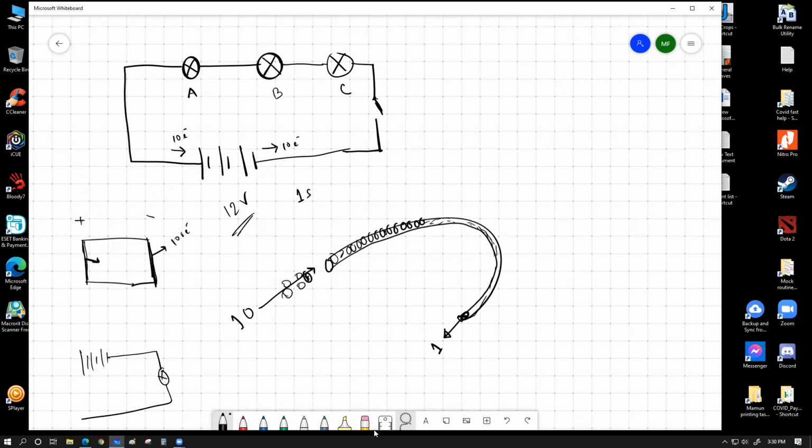You can assume actual or, realistically, 1 coulomb of electrons coming out of the negative side. Either way, 12 volt means 12 joule per coulomb, which means 1 coulomb of charge is going to have 12 joule in it. This charge starts its journey from one end of the battery, and over the process it spends its entire 12 joule of energy, converting its electrical energy to other forms. Eventually, when it is received back into the battery, it has zero electrical energy left. That's the basic idea of 12 volt.